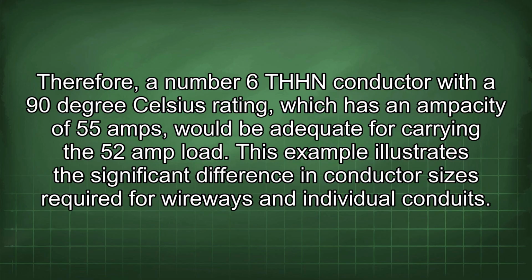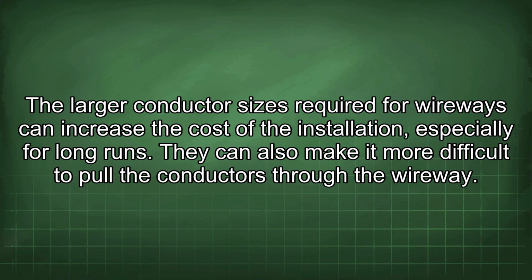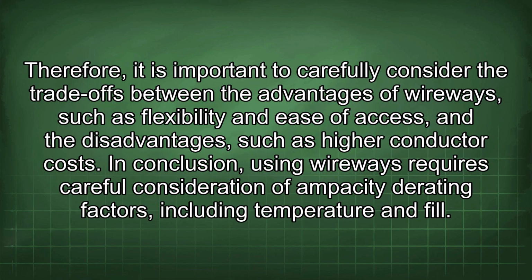This example illustrates the significant difference in conductor sizes required for wireways and individual conduits. The larger conductor sizes required for wireways can increase the cost of the installation, especially for long runs. They can also make it more difficult to pull the conductors through the wireway. Therefore, it is important to carefully consider the trade-offs between the advantages of wireways, such as flexibility and ease of access, and the disadvantages, such as higher conductor costs.